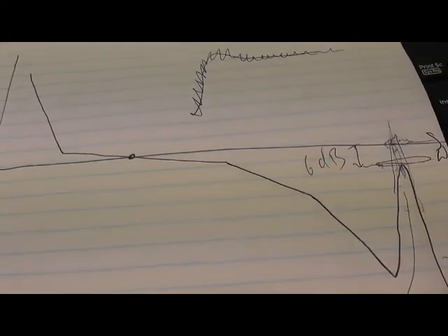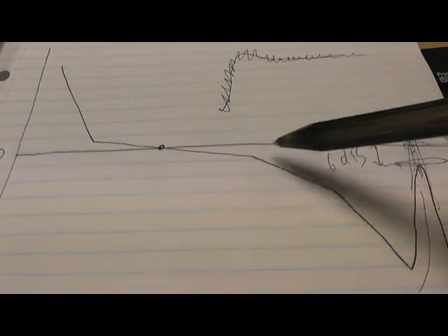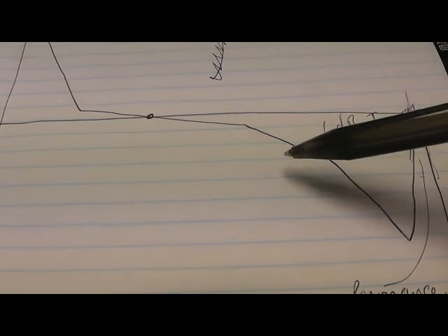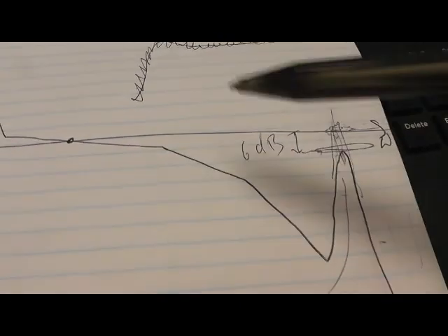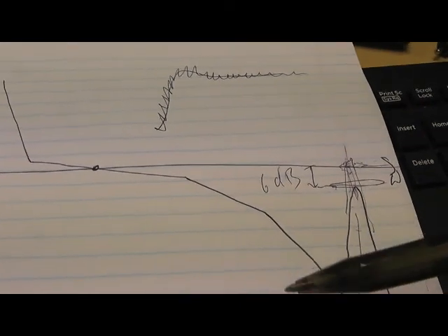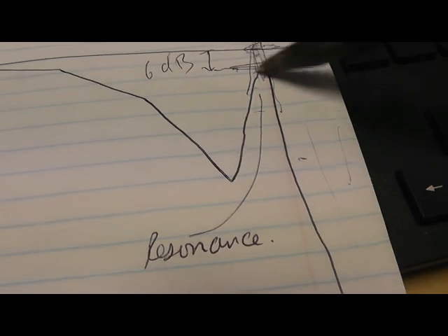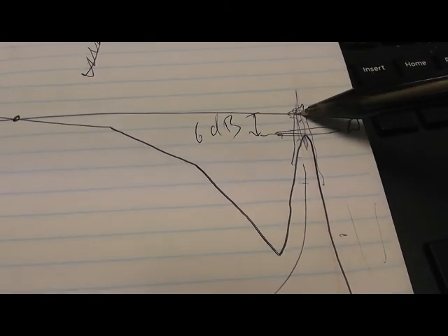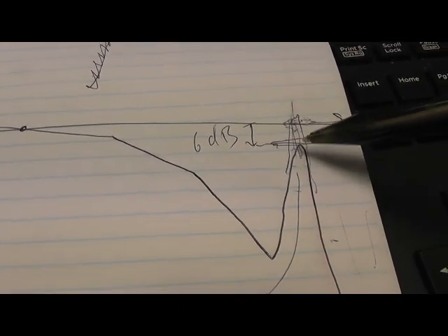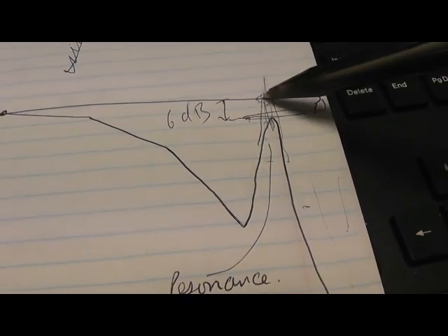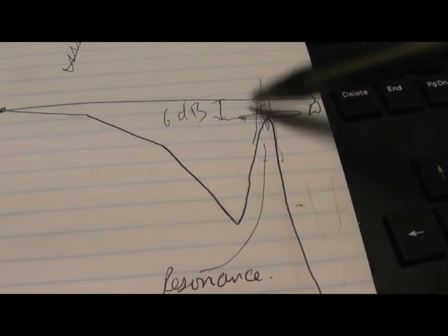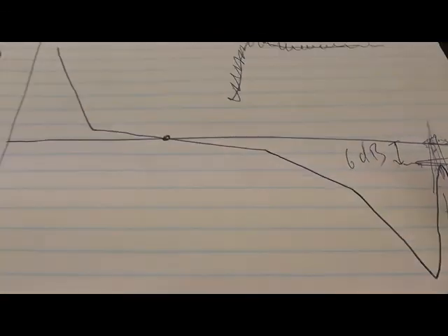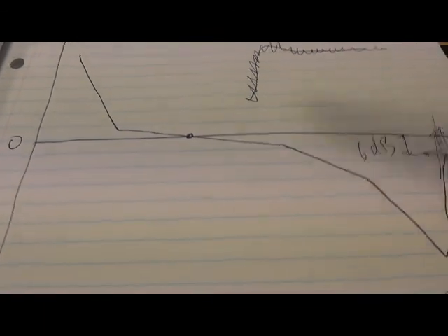And this is another restriction: if you wanted to add more phase advance, a second phase advance, this is possible, but you've got to be careful because phase advance has a high frequency gain, as we've just seen, and what that will do is move this up. So if you've got resonances and you put in more than one phase advance, you might find that instead of stabilizing it more, you actually end up destabilizing it at the high frequencies, even though it's stable at the unity gain point.